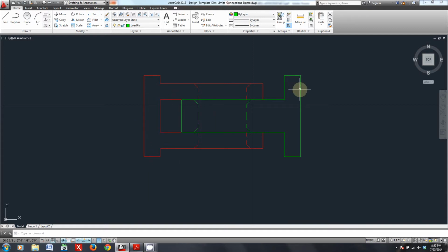Of course, if you're going to mill your male connection, all you have to do is cut out these areas on these sides, and then you pretty much just have this thing that you can put through a drill press. However, on the female connection, you have to cut out this whole inside area here, as well as on the outsides. So cutting through the center area can be quite a limitation, especially considering the fact that you're trying to get an end mill to go all the way through this thing.